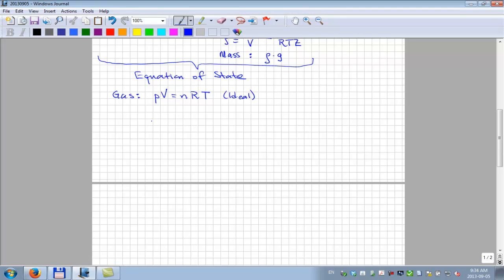And then we have a more generalized form that deals with all gases. So we call this real gases. That would be also at high pressures, lower temperatures, but it's behaving like a gas, where we add this Z factor, and we'll tag on the G there, the gas Z factor, which came to us from January 1941, I believe, the Standing-Katz Z factor chart, which is a function of pressure, temperature, and composition.